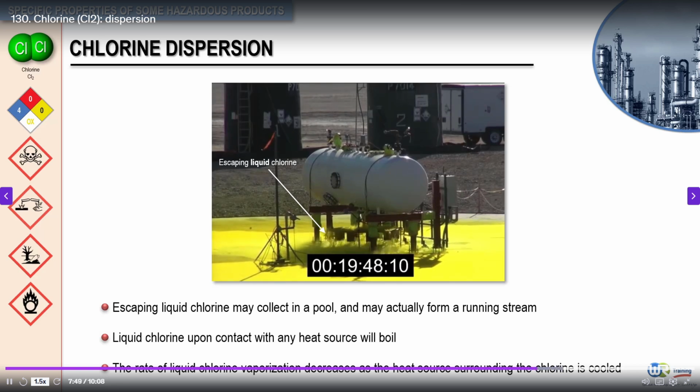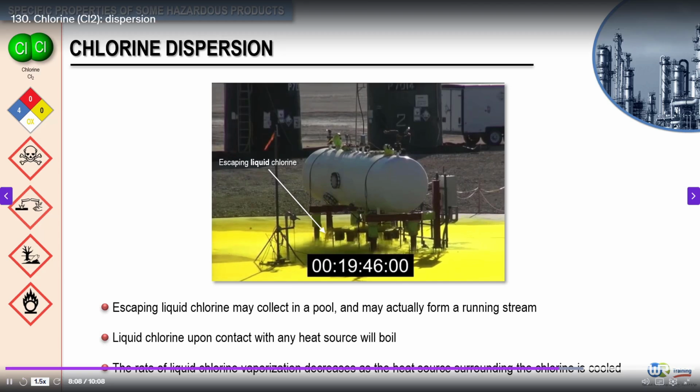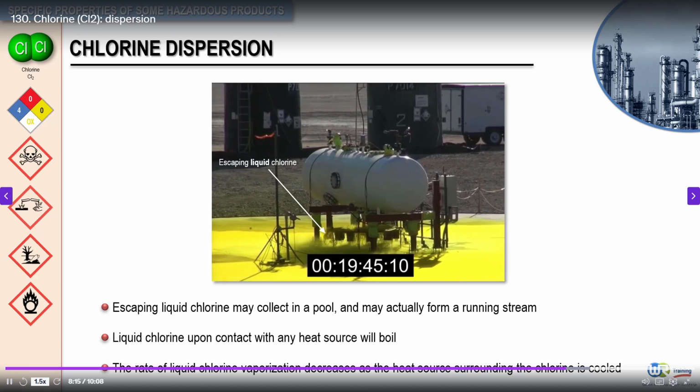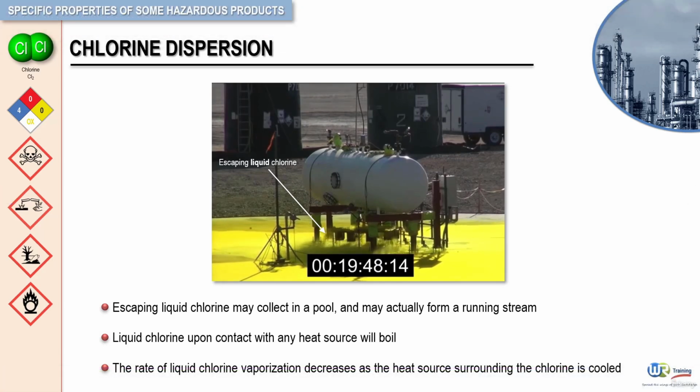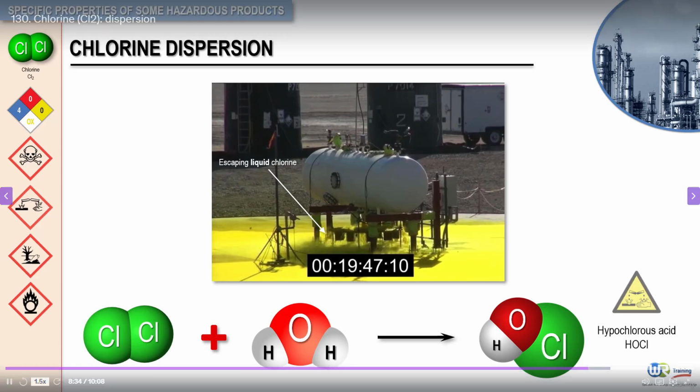For now, keep in mind, since water in bulk, as used to fight fires for example, provides the vast heat source for evaporating liquid chlorine, any liquid chlorine falling into water should be assumed to react. For this reason, water should be prevented from coming into contact with the pool of liquid chlorine, and should be prevented from flowing into water drains. In addition, attempts to knock down a chlorine gas cloud with water should not be made. Recall, liquid chlorine will react with any moisture to form hypochlorous acid, a very corrosive substance.